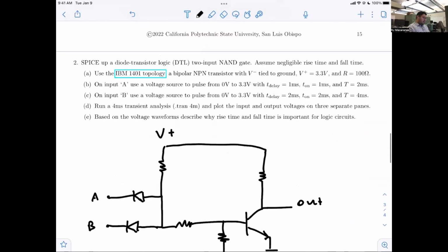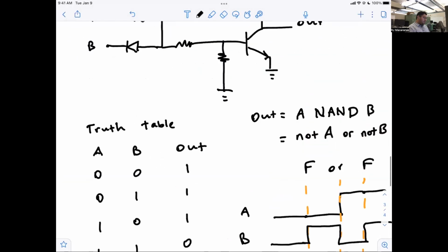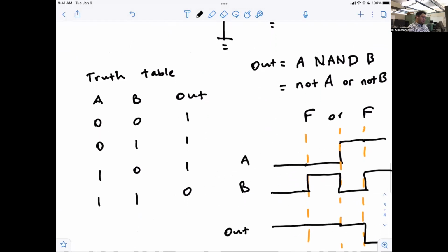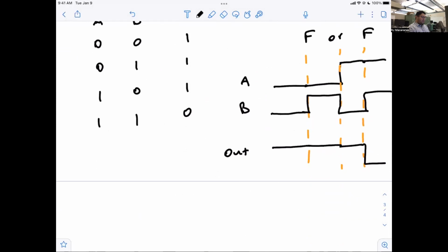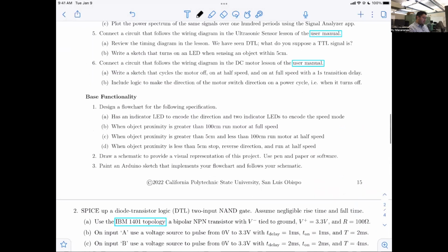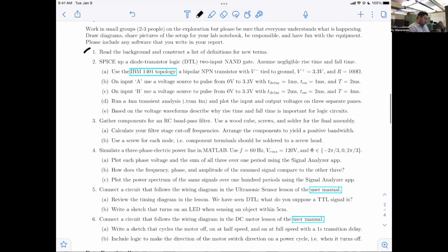And it gives you instructions on how to set up these pulses, but you're going to use a voltage source, right? And you can change somewhere in the advanced settings to this configuration of a voltage source. Then you'll make some observations on these transitions here and where it might have an unexpected output due to the rise and fall times of our circuit. So we've gone over this.